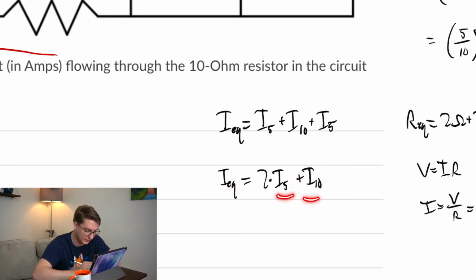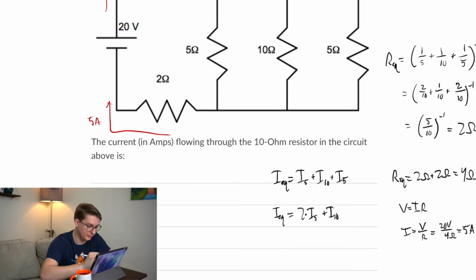So how do we break this degeneracy? How do we end up solving for this? Because we have 2 unknowns, and we want one thing. Well, we're going to have to use the other Kirchhoff law, which is that the voltages over things in parallel have to be the same. So for these two things, when I go in a loop, I have to have the voltages add to 0. I have a current going this way, a current going this way, so one of them ends up adding positively. That's this one.